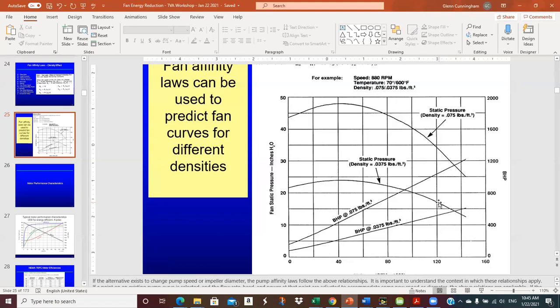And as far as your drive noise is concerned, you should always be putting some type of line filtering on that drive. At a minimum, line reactors, and if it's an extremely noisy drive, you might even need an isolation transformer. We run line reactors. It's just that our system's changed over the years since we first put these drives in. Now the demand is new, so growth has driven us to run at 60 hertz.